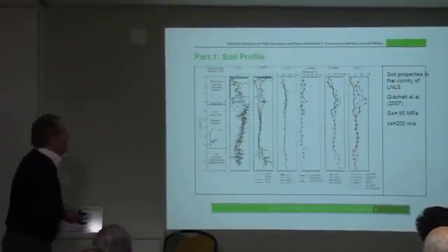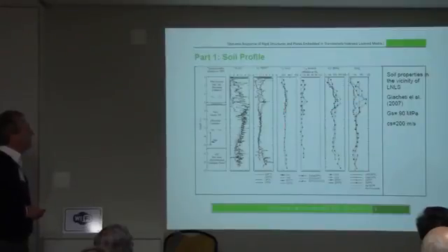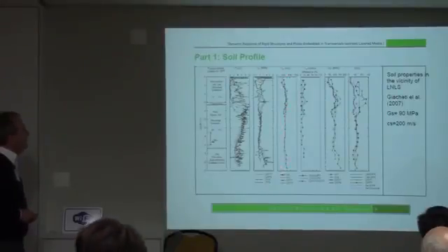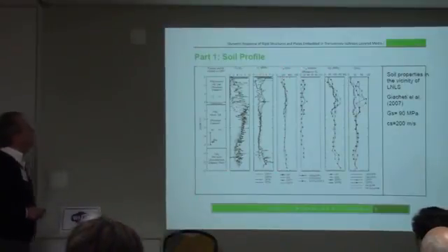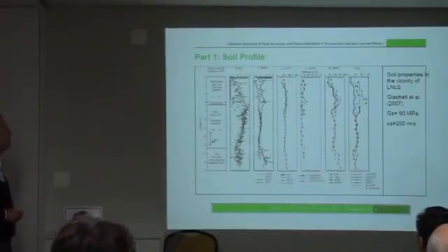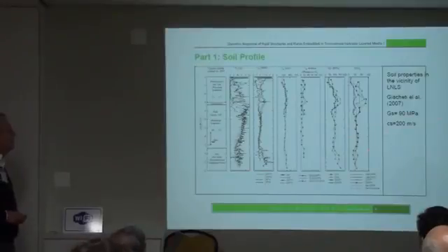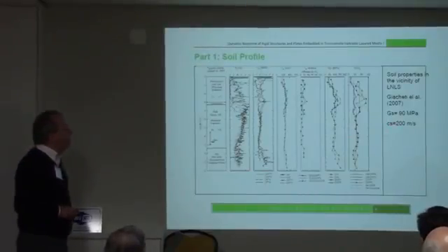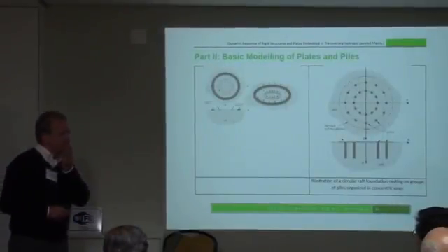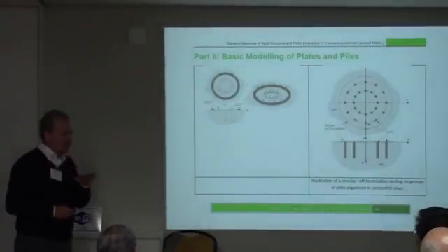So from the soil profile, we did a model, we modeled the microscope foundations. We took data from a colleague that worked here. So we have a profile versus depth. Again, this is the shear wave velocity of the soil. We have almost constant shear wave velocity through the depth here. So we know something about the surrounding soil. It could be modeled in some areas as half spaces. Basically soil or is it rock? It's clay, basically.